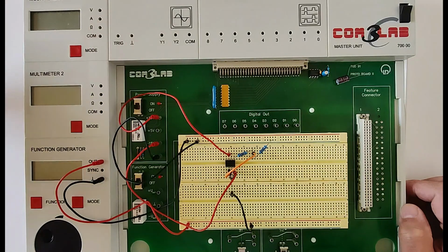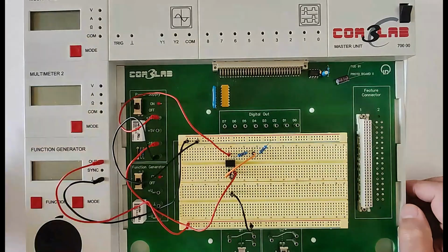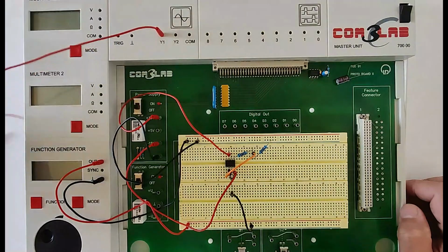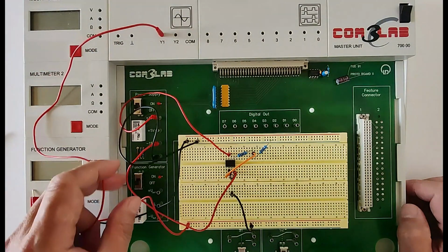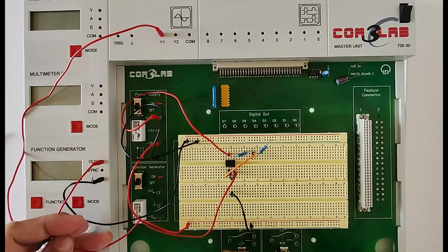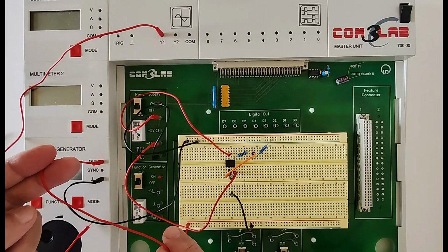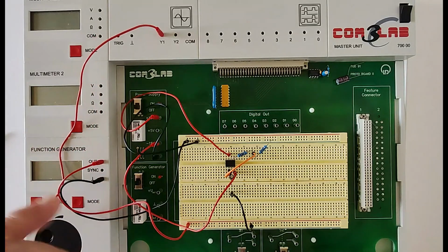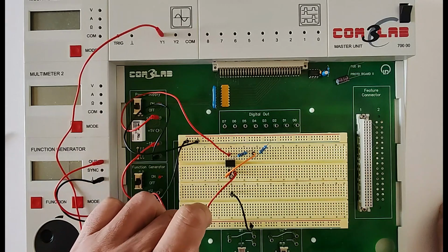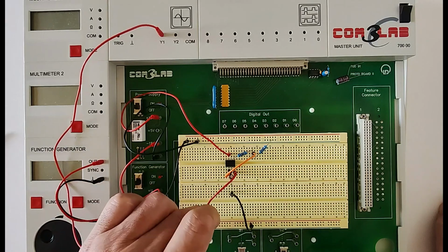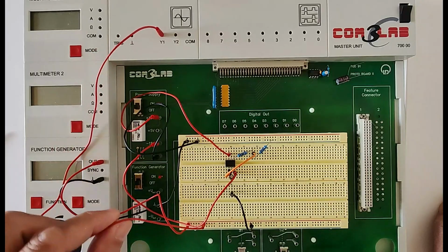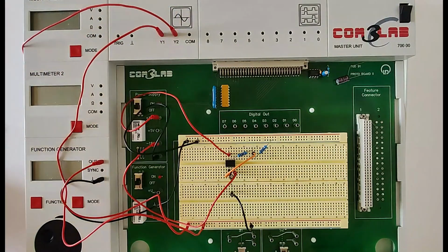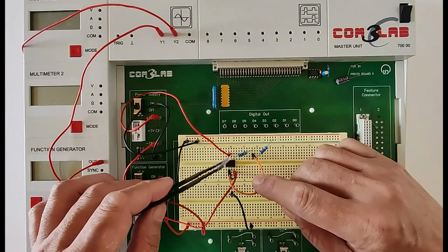So what I'll do is this. For the input waveform, Y1, I will have one wire. This one's connected to the input. Where is our input? Our input is the out terminal of the function generator, which is this one. So I need to connect it on the same line where this function generator is connected. So you connect this one now to the red power rail at the bottom there. That's your input. Now for Y2, which I'll connect to the output, I'm referring to the output of our 741 IC.